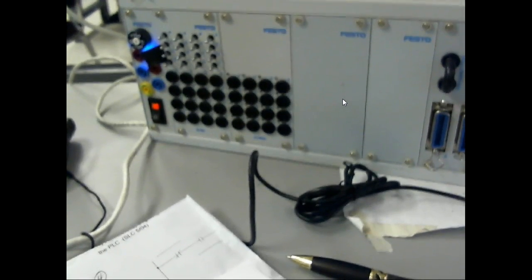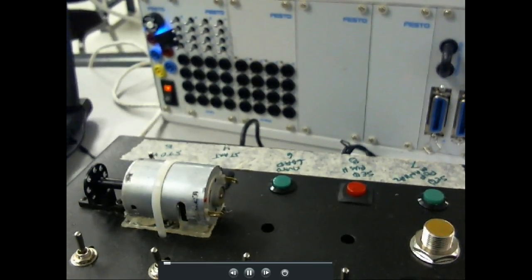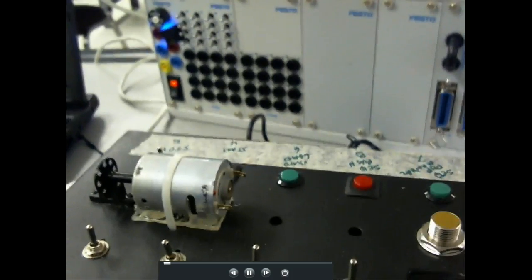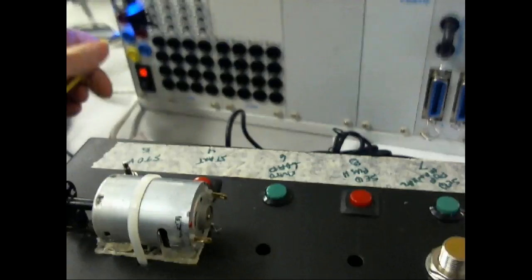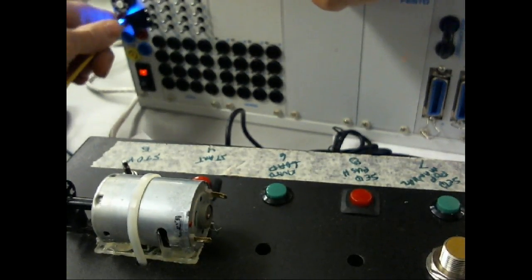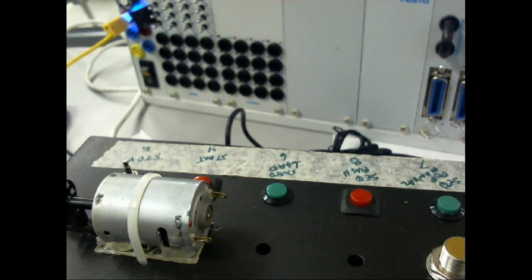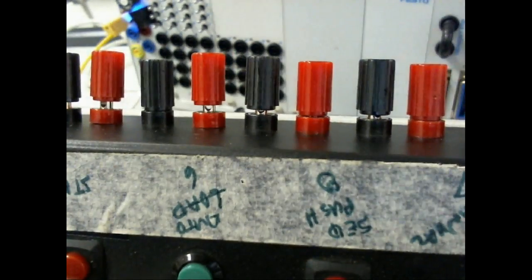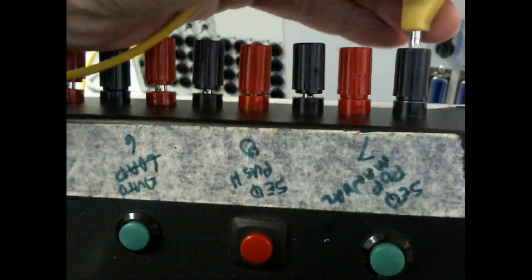Now my input ports on my PLC are set up to sink. So it means all my push buttons I'm going to have to set up to do what? Source, right? Okay. So what I'm going to do here is I'm going to come over here and go to the positive on my output. Let's turn this off right now. And then here's my push buttons right here. Okay. So we're using normally open push buttons. So I'm going to hook it up to common here.